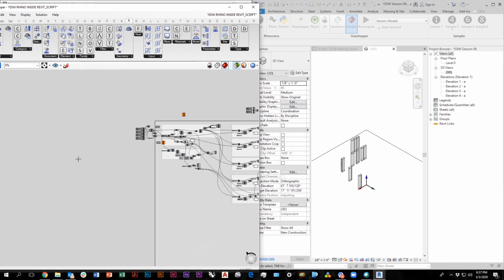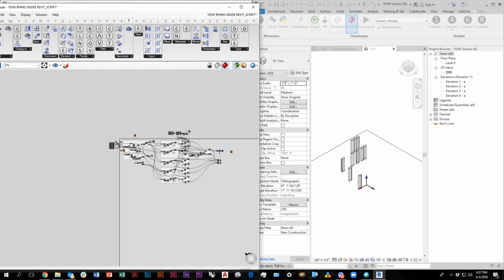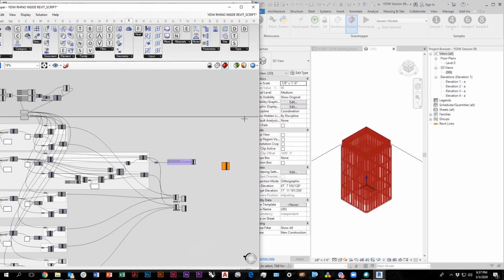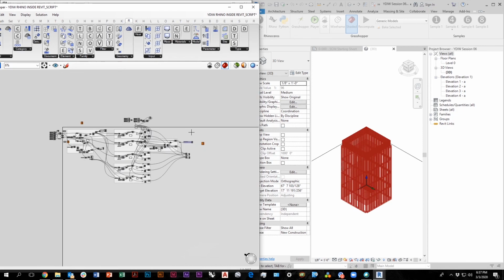So I built the script with no intention of it ever seeing Revit. It's represented as just a simple panel with a hole cut in it. If I were to build this script now with the intention that it would end up in Revit, I would make all of them solid, but still separate them and then say, turn this solid shape into a Revit window using one of these components. Exactly, right. So that's how I would do it.